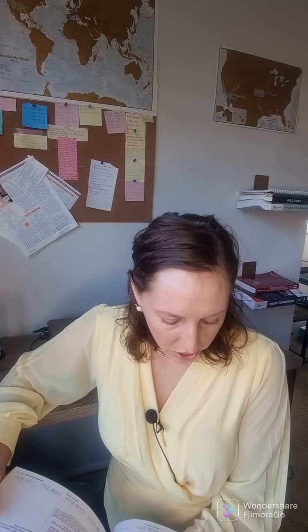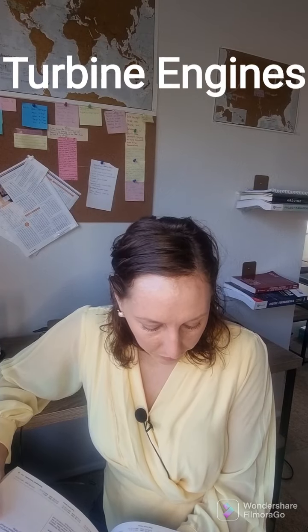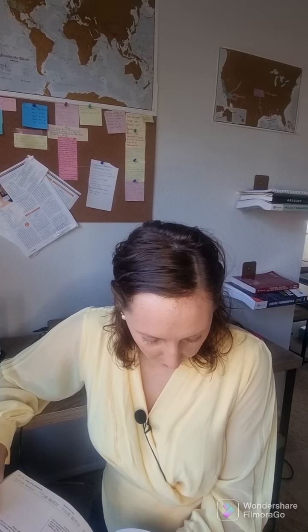I'm Karina, living Lean Six Sigma, and we are studying today the Powerplant 2020 Study Test Guide, starting with the section Turbine Engines. Question: at what point in an axial flow turbojet engine will the highest gas pressure occur? Answer: at the compressor outlet. The highest gas pressure in an axial turbojet engine occurs at the outlet of the compressor. The compressor outlet is the same as the burner inlet.